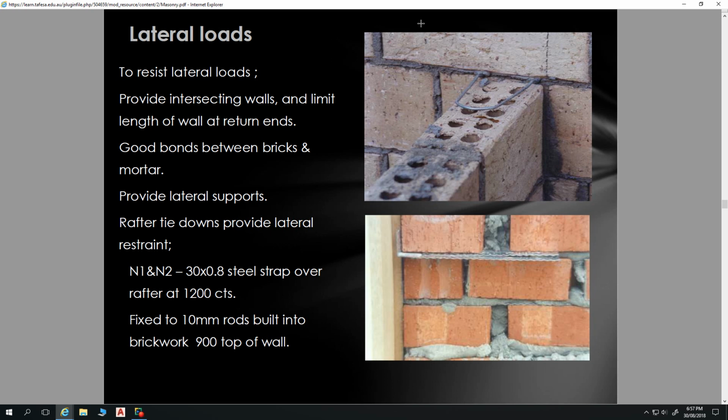In your mortar gap, and I don't have a 10mm rod, but let's call this one a 10mm steel rod, we put a 10mm rod in there, and that rod doesn't quite reach the outside of our mortar, because we don't want that exposed to air, and we also don't want the appearance of a rusty rod on the outside of our masonry.